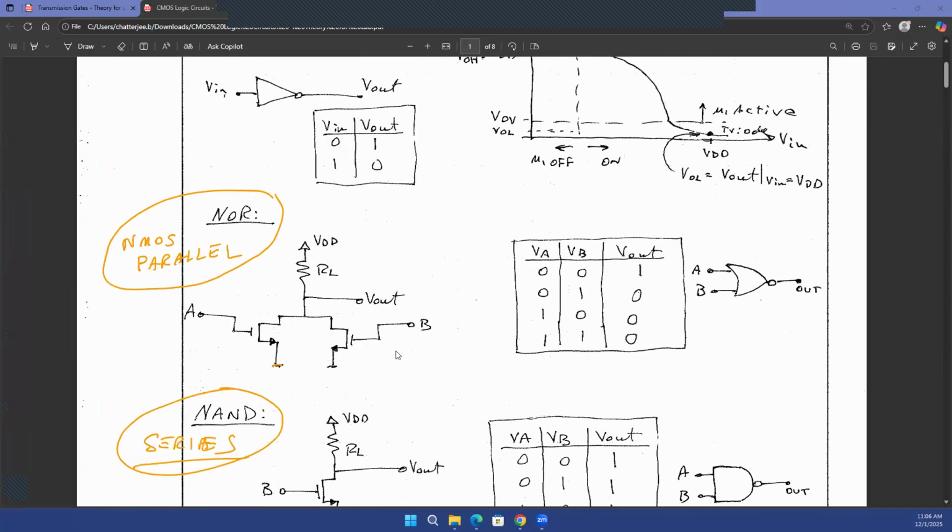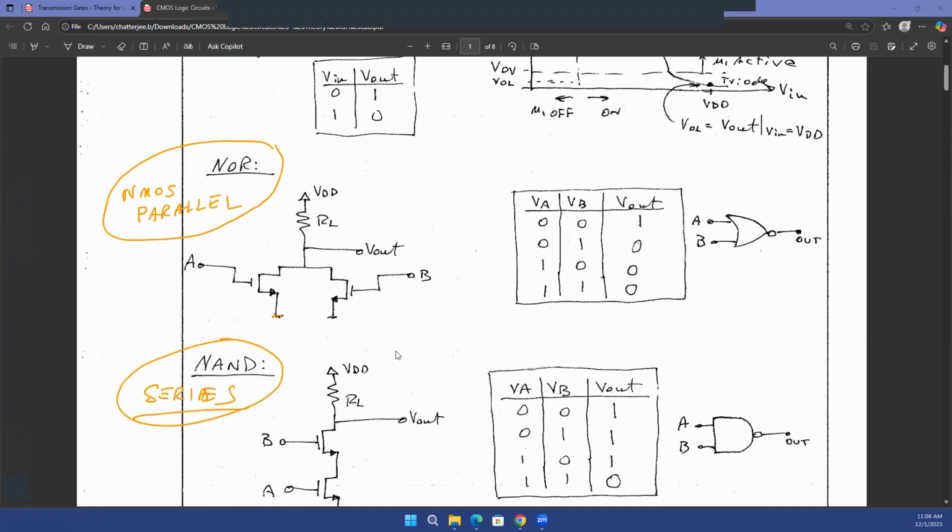All right. So that's just an inverter. Can we build other logic circuits with the same idea? Now, if you think about it, what do logic circuits mean? Let's say, for example, think about the NOR gate for a moment. NOR gate means that if both of my inputs are 0, my output will be 1. In all other scenarios, my output will be 0.